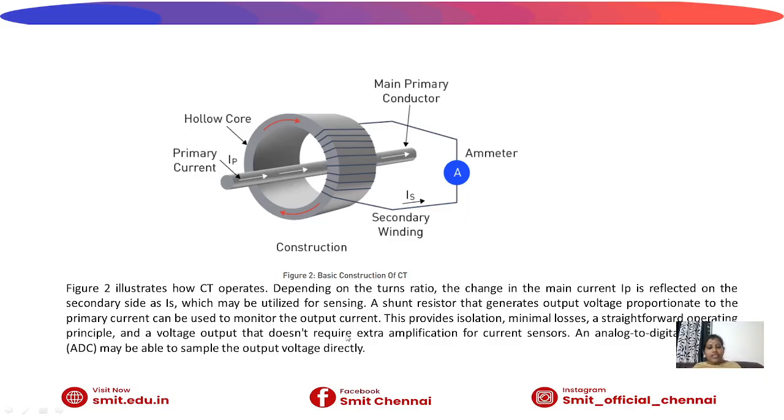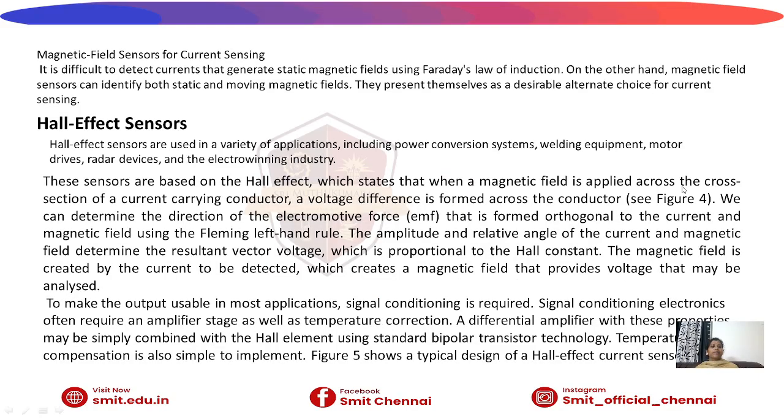An important point: it does not require extra amplification, but with the shunt resistor we need the amplification factor. It needs an ADC to sample the output voltage directly.